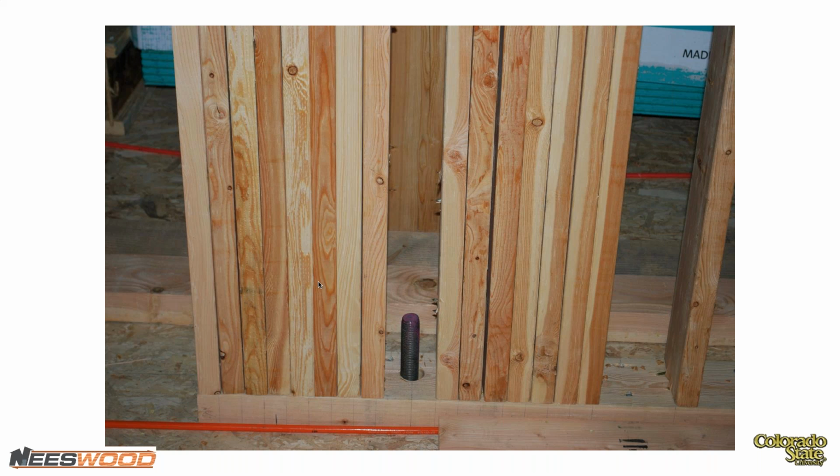The sheathing going on here, and you can see that when we get to the cross-laminated timber example, I would say just keep in mind that in a way we were kind of getting there already with the size of these stud packs, and that's because of the drift requirements. And so it's this overturning that we're imposing on the building.